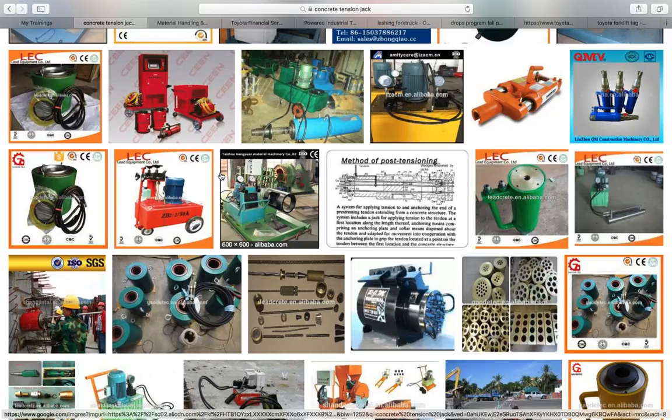Any type of shoring equipment has to be inspected and properly maintained to make sure we don't have any collapses on employees. The same goes for forms and shoring. We have to have reinforcing steel adequately supported to prevent it from falling or collapsing as well. And we have to take certain measures to prevent uncoiled mesh wire from recoiling, or anything that may harm the employee, such as hazardous chemicals and materials with concrete.